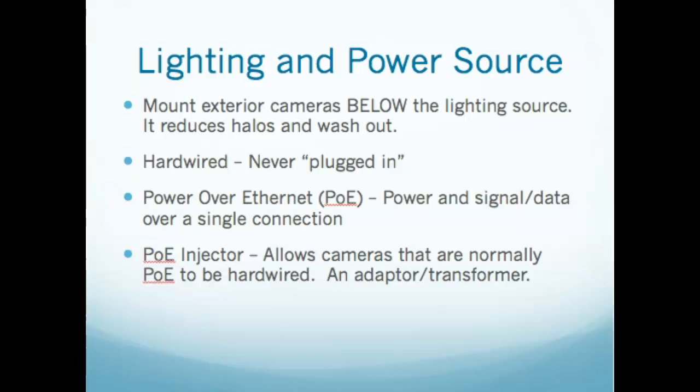And if any wiring or cabling is exposed, you use something called a wire mold or a conduit, and you cover it so that nobody can cut the wiring. But never plug in your cameras unless you absolutely have to. It's just a bad practice, and I have seen so many installers do it. In fact, they even hire an electrician to put a plug on the wall right behind where they're going to put the camera so they can plug it in. And it's at ceiling, normal 8-foot ceiling height. Anybody with a step stool or a stick can unplug that thing.